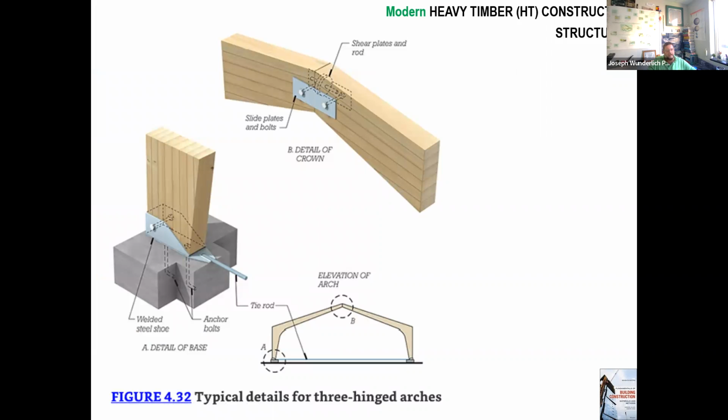Talk about that more in other classes. So this is heavy timber construction and different ways of putting together gusset plates and other things. The connections are always serious. That's normally where most things fail. As students, you're always designing for flexure and shear, and bending and compression and everything. But most structural failures you're going to see come down to connections a lot. And I could talk about that for a while, but I'm not going to here.